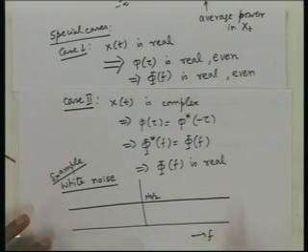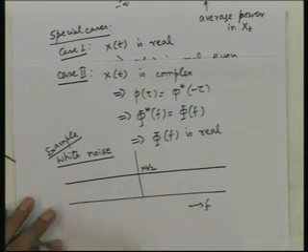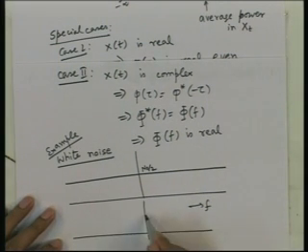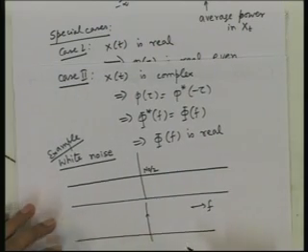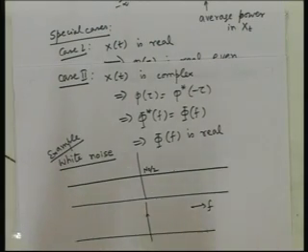So, what is the autocorrelation function of the white noise then? It is the inverse Fourier transform of this, so it is a delta function. That means that the autocorrelation at non-zero gaps is 0. So, if you take two time instances and consider the random variables of a white noise at those two time instances, then the correlation between them is 0. There is no correlation between the value of the noise at two different time instances. So, white noise is basically uncorrelated in time.